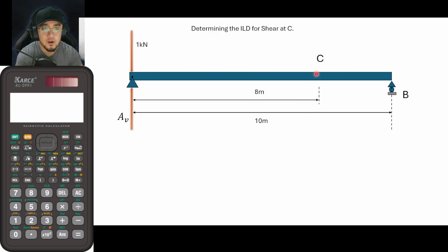So going back here, how can we solve for the shear at this point? Our method here is that we will be cutting a particular section here. So we would be cutting the section here and we would be getting the summation of forces vertical. That will now be the value for VC or shear at C. Our sign convention is upwards positive. If you want to learn about this, better watch our previous video on frames and beams.